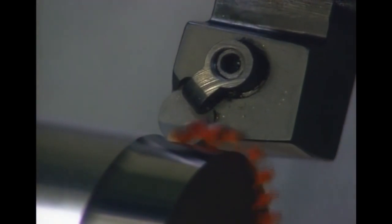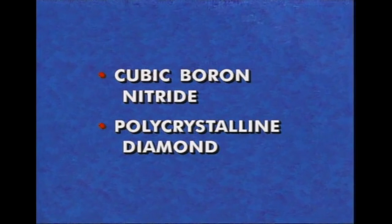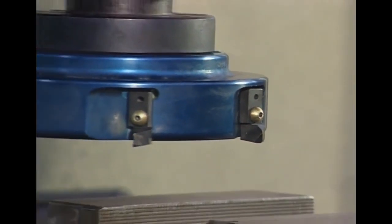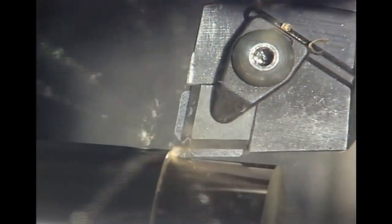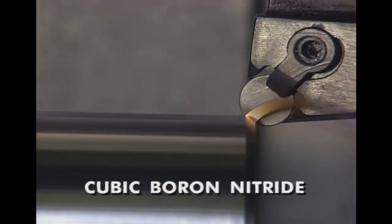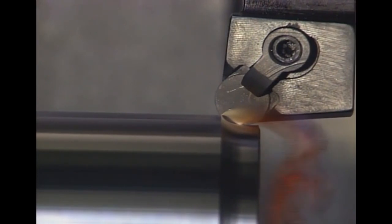Super hard tool materials are divided into two categories: cubic boron nitride and polycrystalline diamond. Typically, a small tip of one of these super hard materials is bonded to a carbide insert base. Super hard inserts may cost 30 times more than a carbide insert, so their use is limited to well-chosen, cost-effective applications.